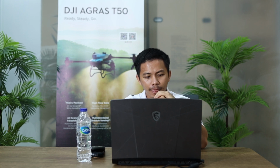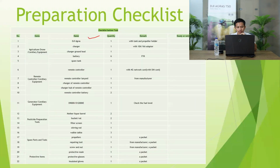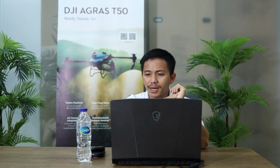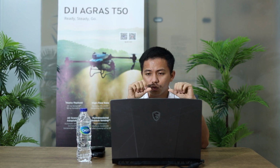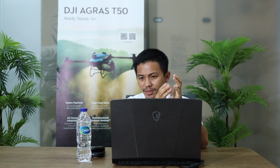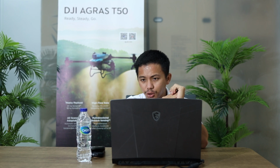Okay. For the pesticide preparation tools, also check the mother liquid barrel, everything, all the tools for pesticides. Especially I want to remind you about the filters. I know the drone spray tank has filters for refilling, but you should have some paper filters or cloth filters that help you, especially when you do powder chemical spray jobs, especially if you are having T13 or a previous model.